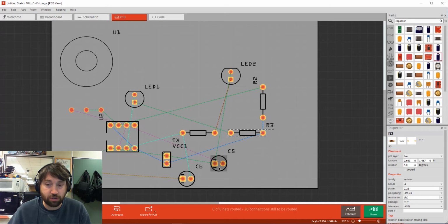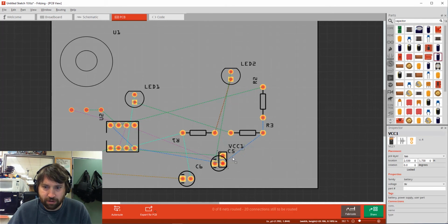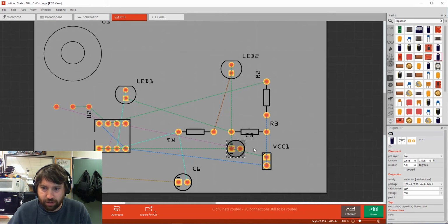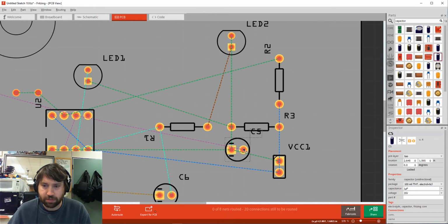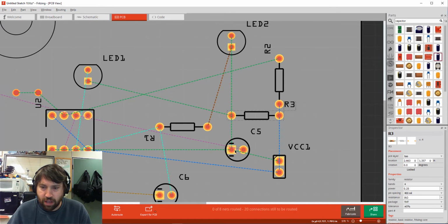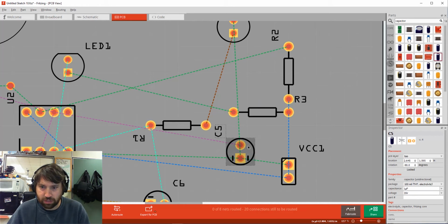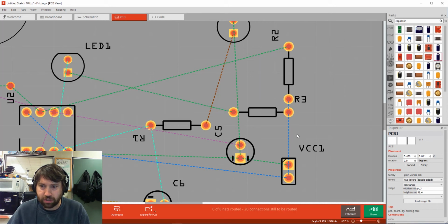Right? And so what we want to do before really anything is just to play around a little bit with the air wire locations. And the air wires won't be perfect, but we want to try to untangle things so we have less overlaps. Right? I think this would actually be a good example of how we could problem solve. Here I've got a couple overlaps. I've got the purple overlapping with the green, and I could solve that by rotating this object one time. But then I also have this green wire wants to overlap with these other green wires. But we notice that also connects here.